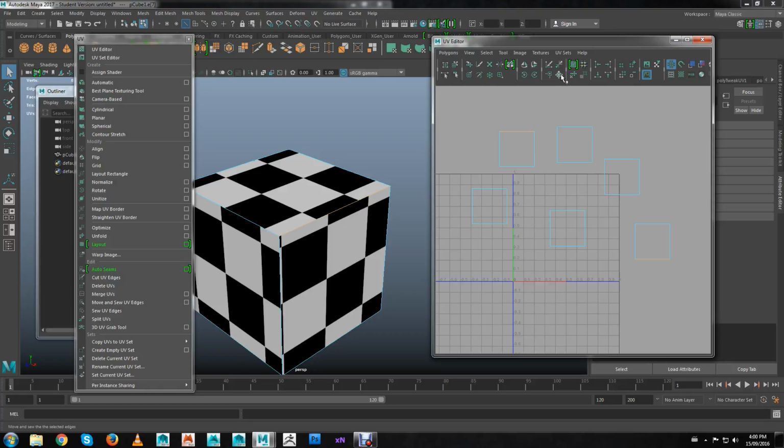It's this button here, the square that looks like it has arrows running through it. What this does is it takes one shell and moves it and sews it to another shell that it's corresponding to. Or edges. So if I grab this edge and say, okay, I want to sew this edge to this edge, it will take the smaller of the two shells and move it to the larger one and sew it to the edge. So watch what happens when I click this.